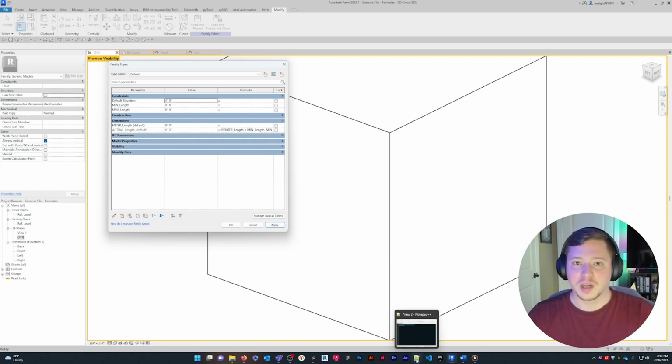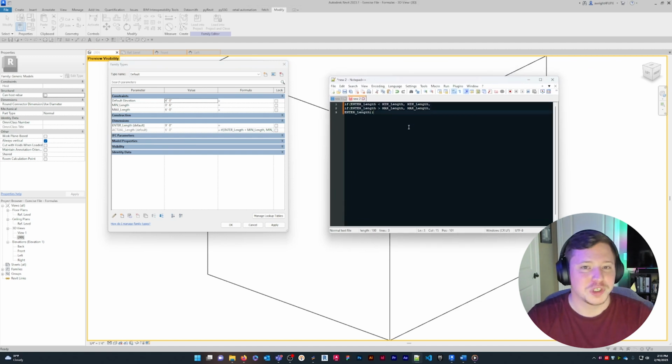And that formula will work in most cases, but what if you want to restrict a user to a certain increment within that range? What if our cuboid can range from 6 inches to 72 inches, but only be adjusted in 6-inch increments? Let's take a look at our last line, the else if. We can use some simple math here to force the validation to only accept lengths at our specified interval by adding a round modifier, and then dividing and multiplying the entered length by our desired increment, like so.